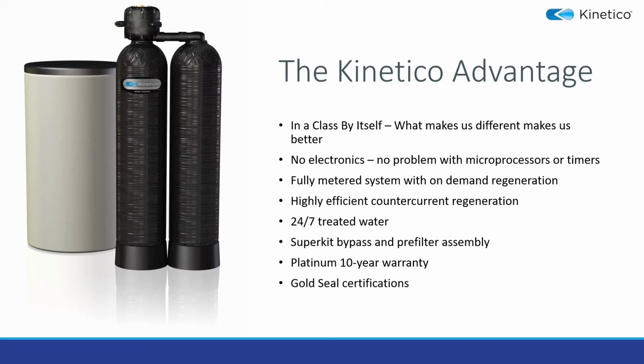However, Kinetico softeners offer 24/7 treated water. You will notice the units have two tanks. As one tank goes into regeneration, the other tank will kick in and go into operation. This provides no interruption in service regardless of usage. Now, because of the two tanks, this system will use 100% soft water for regeneration. This allows for a more effective and efficient regen by using less salt and water. Essentially, the unit is using clean water to clean out a dirty unit.